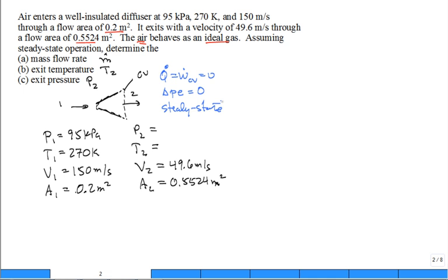All right, so our energy balance equation, should I write down the whole equation? You got it? So it would be that 0 is equal to m dot times h in minus h exit plus specific kinetic energy in minus specific kinetic energy exit. Just one mass flow rate. What's in is out, and then the energy balance gives us the relationship. Why didn't I cancel and say the change in kinetic energy is 0? Well, it wouldn't be much of a diffuser then. The purpose of the diffuser is to slow it down. When it slows down, the kinetic energy drops a little bit. Okay?